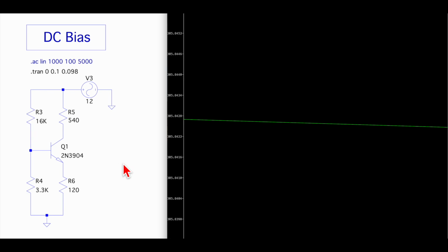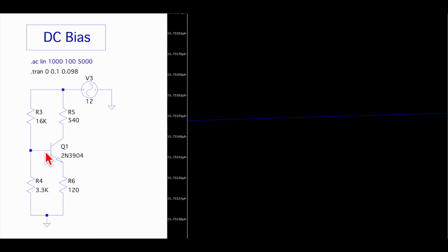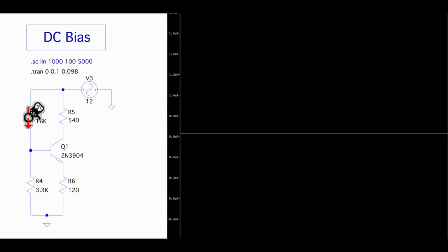So that will obviously affect things. It means instead of having nearly 60 microamps on the base, we've only got nearly half that, 33.7. Because we were bargaining on 60 microamps here, that's why we've got 623 microamps going through the voltage divider.